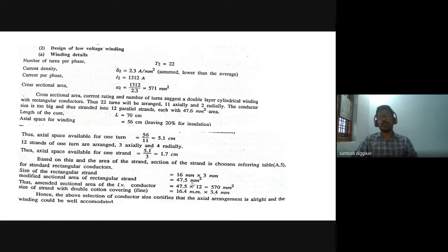Now, no load current. If you calculate the no load current for this one, it is 0.42%. It is within the performance range, below the limiting value of the performance range. Therefore, again, the dimensions which were designed for the magnetic frame are okay.